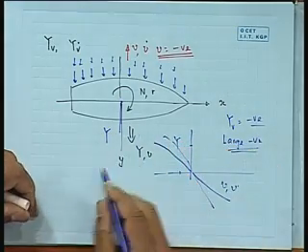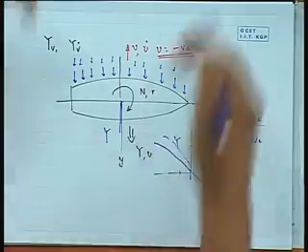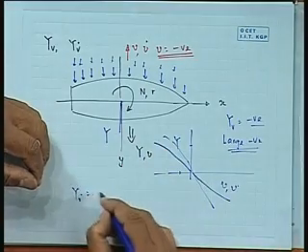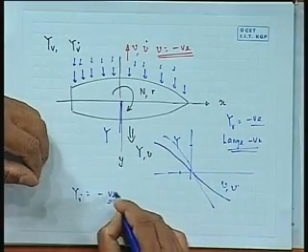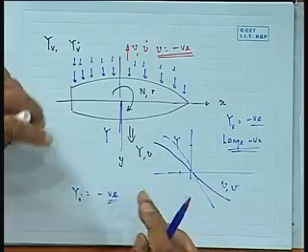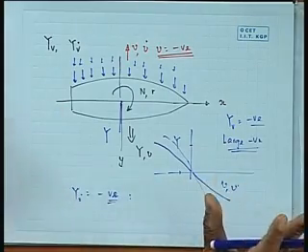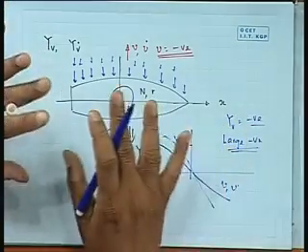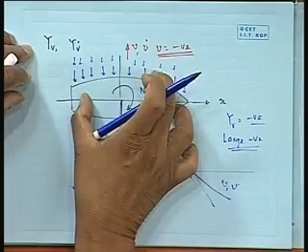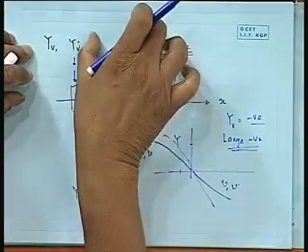Okay, so I get Yv dot to be large, negative. So I get Yv dot to be negative. Now, is it large or small? I want to answer this question. See, Yv dot is nothing but like an added mass. Yv dot is actually, because I am given an acceleration on this side, there is a reaction force.